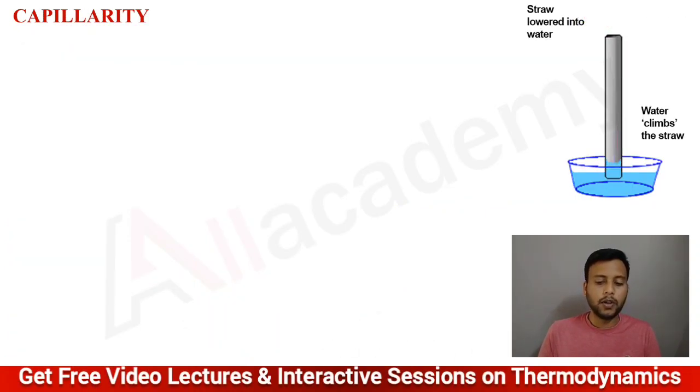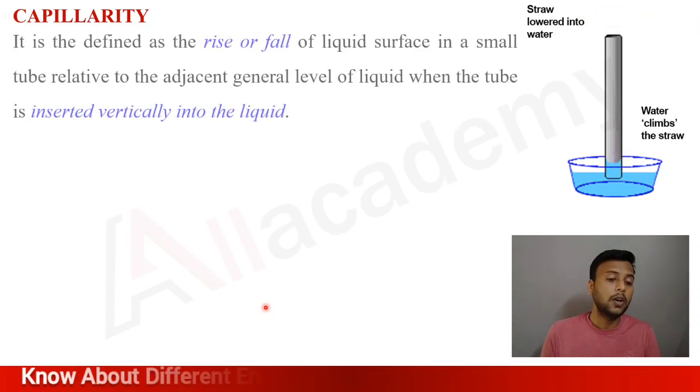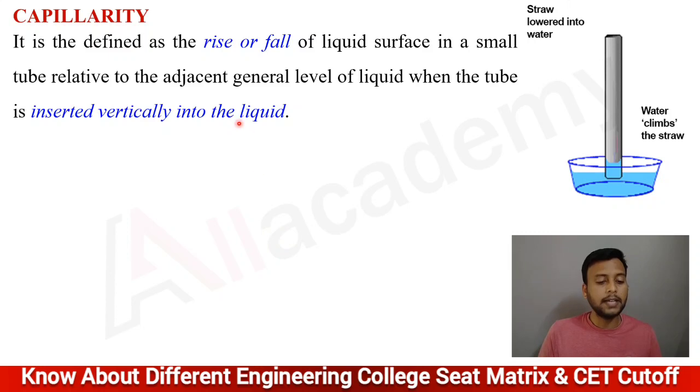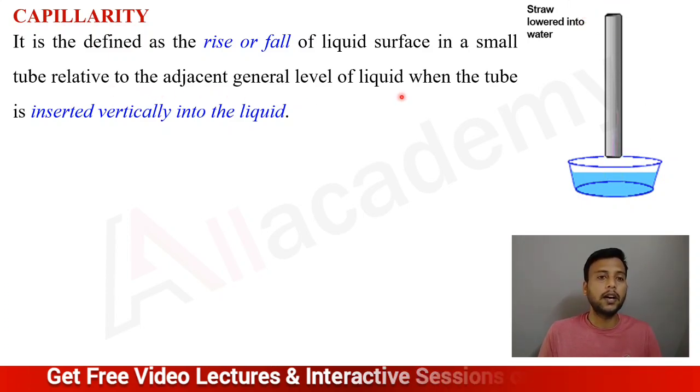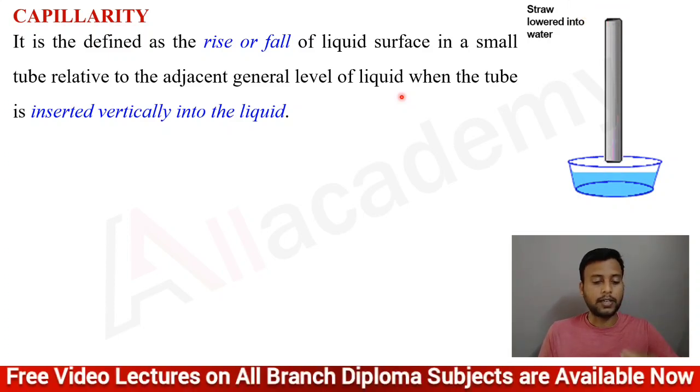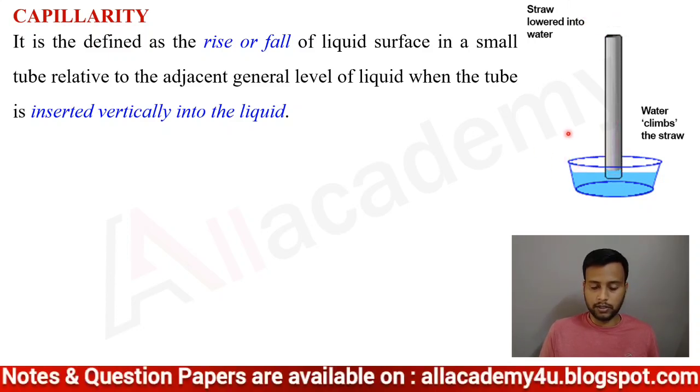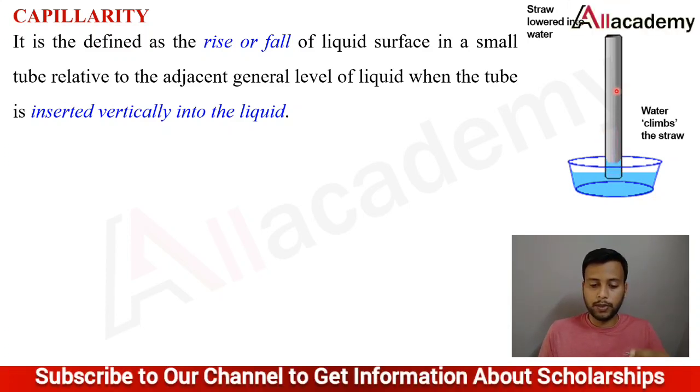The next very important topic is capillarity, rise and fall. Before that, what is capillarity? Capillarity is defined as the rise or fall of a liquid surface in a small tube relative to the adjacent general level of the liquid when the tube is inserted vertically into the liquid.